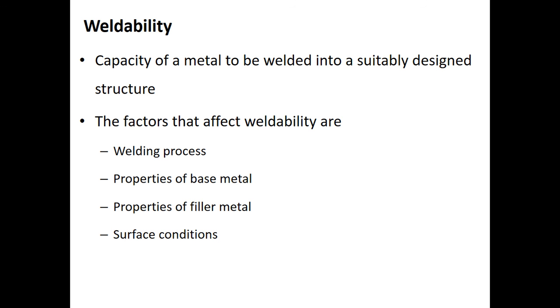For example, some metals can be easily welded, but some other metals or alloys are difficult to weld. For example, aluminium can melt easily and is regarded as one of the nice metals for welding. However, copper has high thermal conductivity, and the heat is transferred faster from the weld zone, making it difficult to make a weld joint.